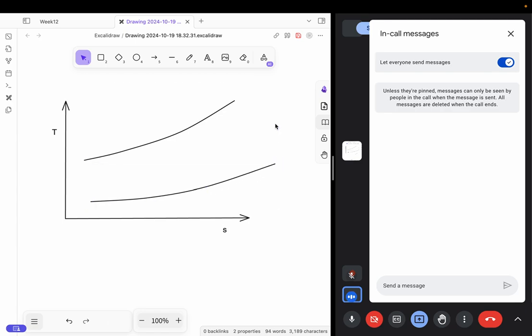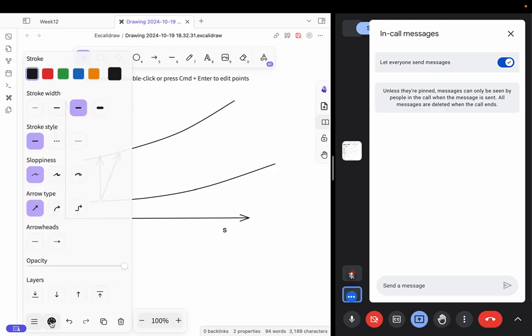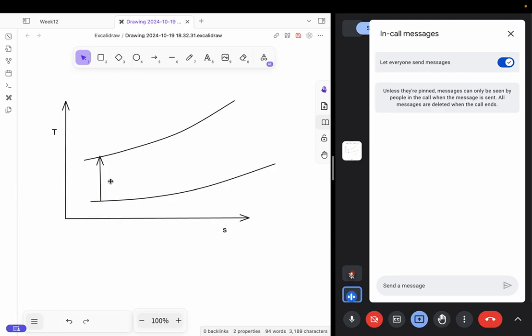Okay, now let's see the different processes. Ideally, you would undergo an isentropic process. This is the first process: the compression process is isentropic. But in real systems, we do not follow that. We'll follow some different process, because of which I'm denoting this with the dashed line; we'll do those lines later. First, let's draw an ideal Brayton cycle and then we'll explain it. First is this isentropic compression process, and then you have a heat addition process that is happening at constant pressure. Let's say it comes to this point.